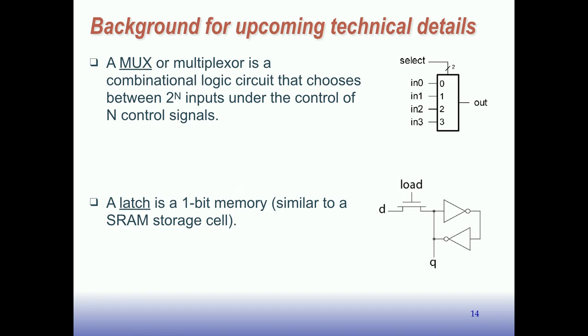And the way it works is there are so-called cross-coupled inverters. There are two inverters in an endless ring here. And the reason we do this, if we want to store a value, we put that value here, and it gets inverted and sent over here, and then gets inverted and sent back. So it gets reinforced. This is like the idea of restoring logic gates, only in a feedback loop, so that if this signal gets disturbed at all, it'll get reinforced back to its original value. So this is a very stable way in CMOS to store a value, assuming you can get the value that you want onto this node. Then it'll be held, as long as the power stays on, as a very robust remembering of that value.